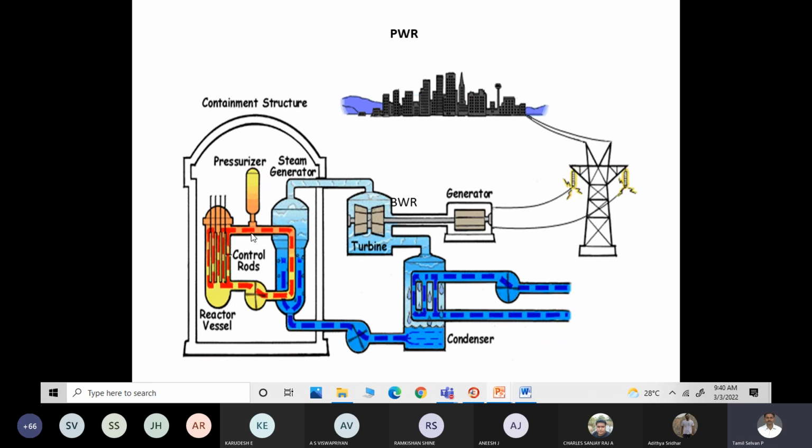Now, see, listen here. These were the flow of the hot coolant in nuclear reactors, right? So again, you can see here convective heat transfer from the hot coolant to the surface, and from the surface to the surrounding water. A combination of conduction and convective heat transfer is there. All of you are able to see this. This is a small pressurized water reactor which you have studied in power plant engineering, right? So the convective heat transfer takes place from the hot coolant to the surface, and from the surface to the water. So the water gets converted into steam, and it runs the steam turbine.